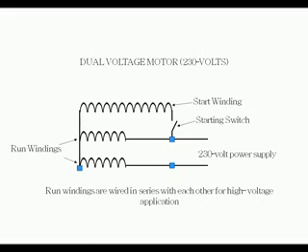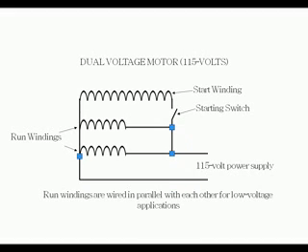Single-phase open motors are mostly residential and small commercial. Residential motors operate at 115, 208, or 230, and commercial motors may go up to 460 volts. Some motors are designed to operate at one of two different voltages. They're called dual voltage motors. You have to be really careful wiring these. Dual voltage motors are wired differently for each voltage. Some motors have reversible rotations.